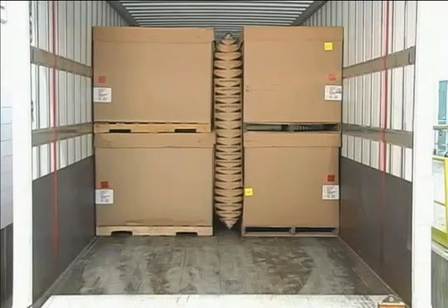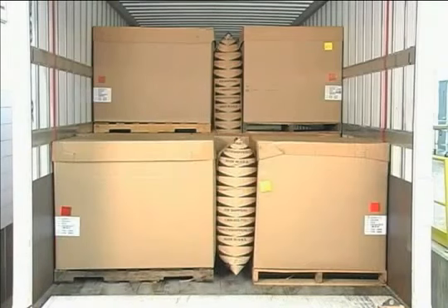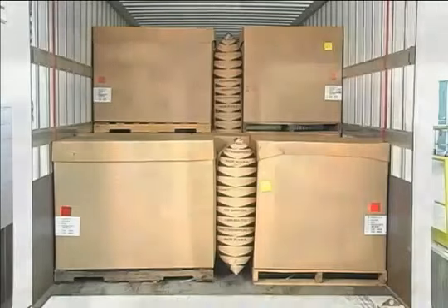For step-up and step-down load configurations, the airbag should cover the entire surface between the double-stacked pallet loads. This prevents the loads from moving towards the front or rear of the trailer. In addition, an airbag must be installed in the last row between the last two pallets of product. The positioned airbag keeps bottom stacks locked in place to prevent the load from shifting towards the rear of the trailer. Once the airbag is in position, verify that the loads are secure.